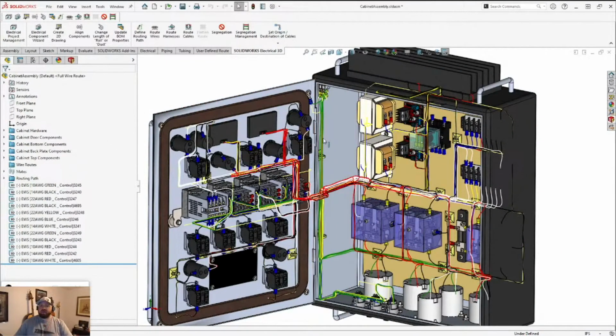Or you can go in and manually edit that if you don't want to have to go back and redo it. I will say a little asterisk next to that manual, right, you can edit those just like you could with any other kind of sketch line. But if you delete anything and reroute or just hit reroute, it's going to delete anything you did manually. So if there's anything manual that you want to tweak, always save it to the very end where you're not going to want to manipulate and change those sketch lines later on.